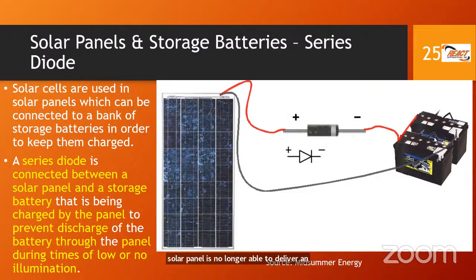So what may happen is that the battery may now start to send power to the solar panel, right? So to avoid that, you put a diode, and you may recall what a diode does. It allows electrons to flow in one direction only, a regular diode. So that's what you do, a sort of check valve operation. You put it in to avoid the battery from somehow trying to power the solar panel. That's not what you want to do, right?